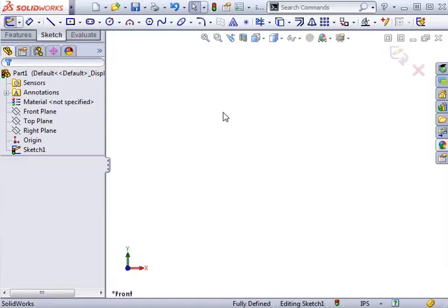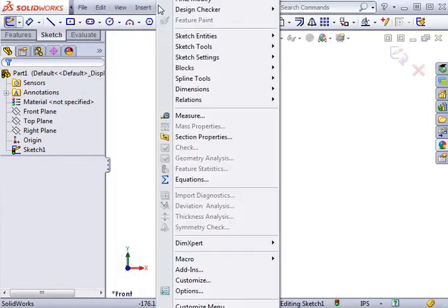A conic is a figure formed by the intersection of a cone and a plane. The Conic tool in SolidWorks lets you define a conic curve in a 2D sketch based on endpoints and a rho value. Just launch the tool from the Tools, Sketch Entities dropdown,